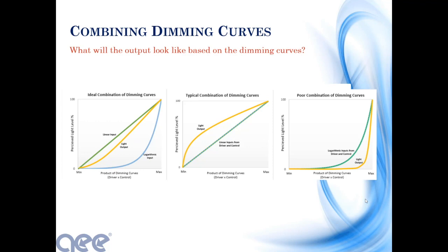So this is important when you have control devices. The people are turning and punching buttons and expect things to happen. The same as when you want to dim something, you turn it all the way to its lowest setting, but the light's still on and you expect it to be close to 0. So what I'm really saying is there are different ways of dimming, and a logarithmic and linear type dimming protocol together are typically the best as far as user interaction with a dimmer.